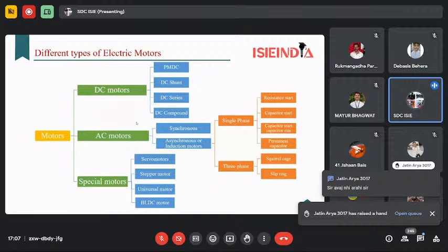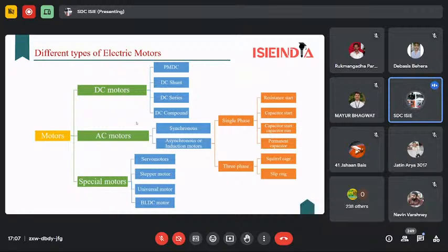As we are using a DC motor, we provide a power supply to the stator as well as the rotor, whereas in AC, we provide power supply only to the stator. We do not provide power supply to the rotor part in an asynchronous motor, whereas in some synchronous motors, we provide power supply to the rotor part also for the initial thrust. But we have seen a lot of drawbacks in the brushed motor: periodic maintenance, not supporting high power density, less efficiency, poor heat dissipation, and many more.